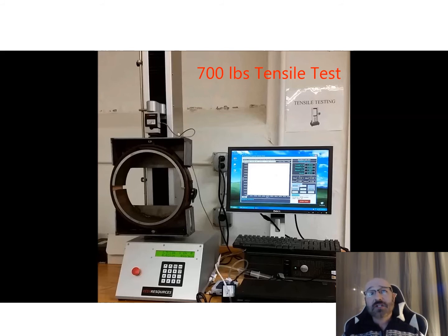So I decided to go for my ladder straps with a glass-filled nylon, a DuPont ST801 material for these ladder straps. And I wanted to test these in a realistic application, which is more expanding than pure tension. So as the user braces off the belt, it creates a force, which puts the ladder strap in tension. We can do the calculations to figure out what that pure tension is on the strap, or we can instrument that strap with some strain gauges and things like that.